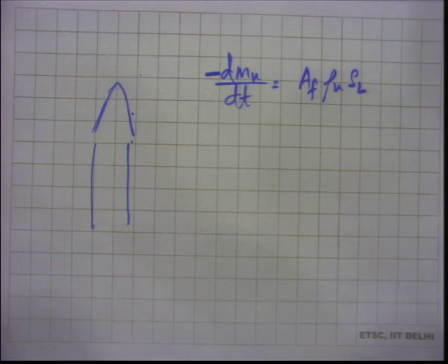So, we had no problem with defining an area, but when you come to turbulent premix flames, suppose we want to do an analysis of turbulent premix flames, then we have to think about some turbulent burning velocity, just as we did for laminar premix combustion. Laminar premix combustion, we had this SL, because SL multiplied by rho u multiplied by area gave you the consumption rate. Consumption rate of the mixture is very important, because that multiplied by the heat of combustion gave you the power that the engine is producing.